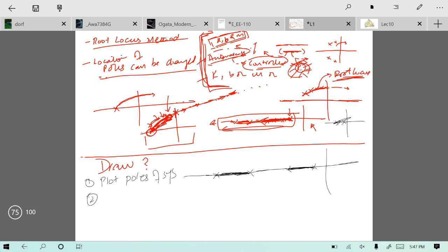So actually root locus is, if you imagine this, drawing the motorways for your roots, or drawing the roads for your roots, which they will follow while you change your gain factor k. So the first point that we know is that there will be a road at this portion and this portion of the real axis. At the moment, we don't know whether this pole will move over here or what would be the direction. We will find out shortly.